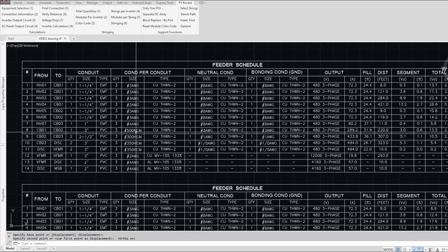It's the maximum amperage anticipated for what we're doing out of combiner 1, but it's not what we base the circuit or fuse on, because it's a continuous load, so we have to add 25% to it. 289.2 times 1.25 is 361.5 amps, and you can see from the chart, number 500 copper, 380 amps, so that's correct. And you can go through here all day. We encourage you to. This is all correct in what we're doing.